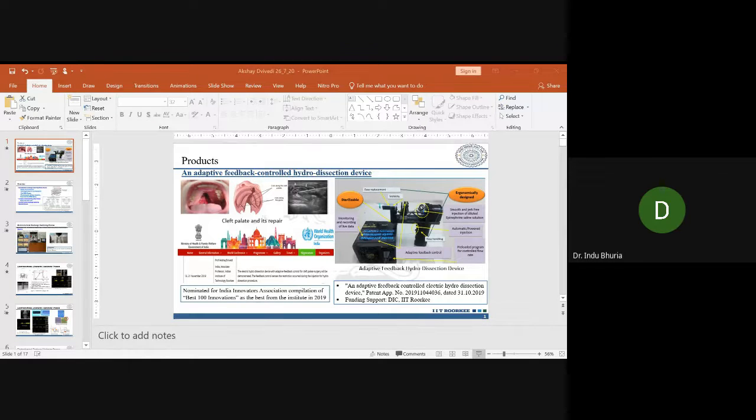All right. So even those people who have no background in manufacturing have learnt about laser, and laser is light amplification by stimulated emission of radiation. Herein there will be light, which is basically photons, and those photons are made to strike a particular surface, and when they strike the surface as a coherent beam of light, they are able to create temperatures on the order of 8,000 to 12,000 degrees centigrade.